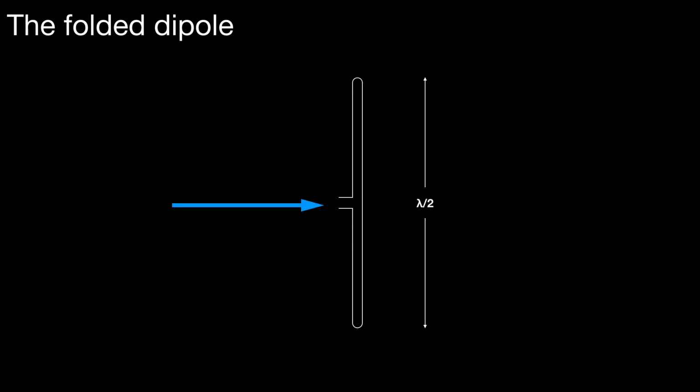So that's from tip to tip, if you like. So the length of actual cable then is closer to a complete wavelength. So despite the name folded, it isn't, if you like, a half wavelength long and then folded down to a physical length of a quarter. It's still physically end to end, if you like, a half a lambda long.